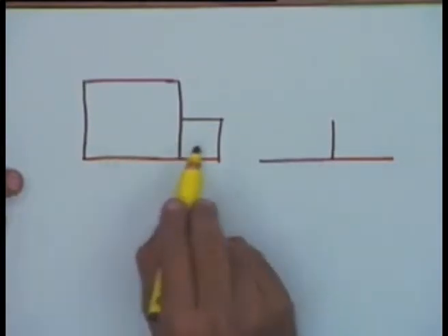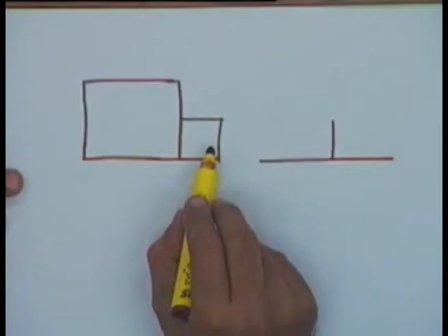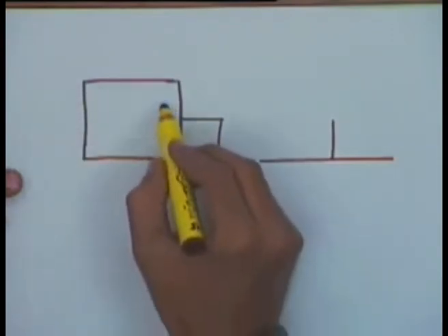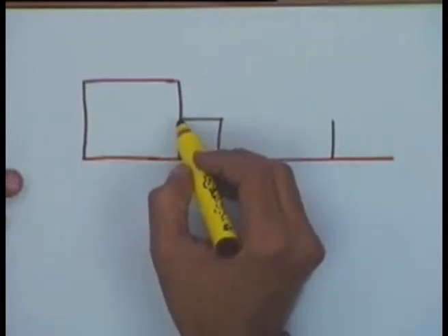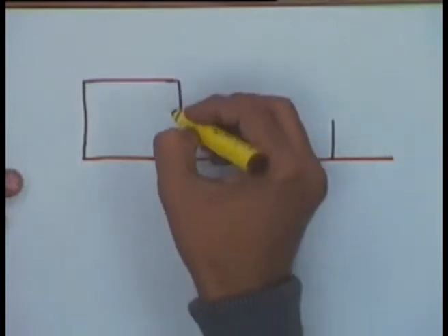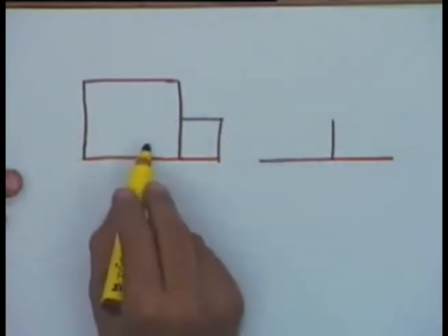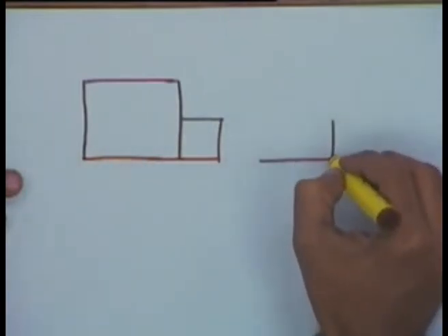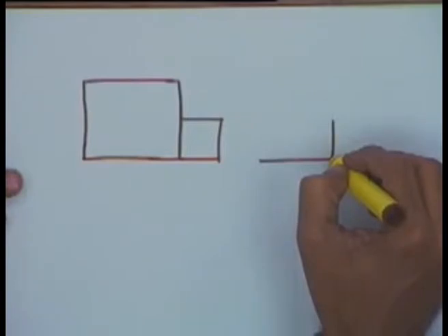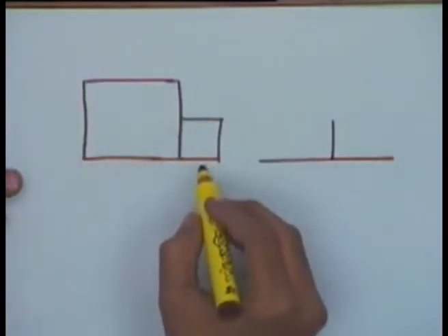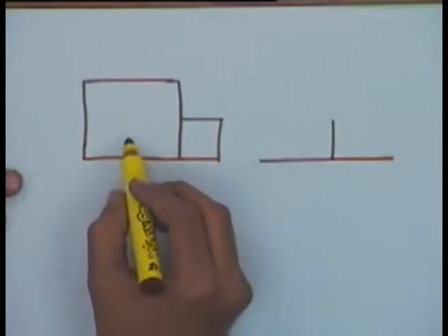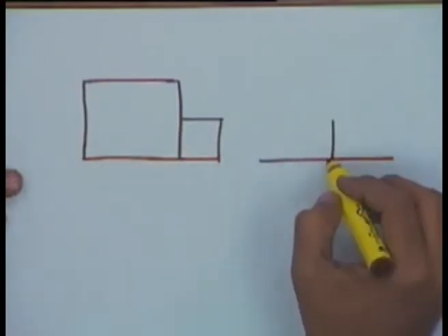Similarly, if I want to define a difference of these two, this set of points minus this set of points, one line will have to be subtracted. So these kinds of problems can come up. If I just consider this single line, this is not really the result one would normally like to have in a solid model. If we have a cube and another cube kept side by side, I would ideally like to say that the intersection is a null set.